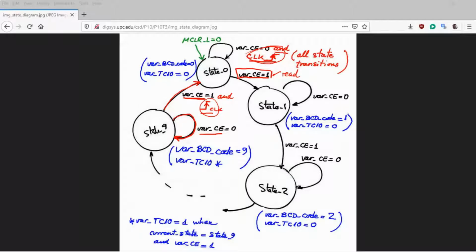So this means that you have to detect that situation as well as you are reading the signal. And to do that detection, you know that you have to go through what is understood as an interrupt to the main program. We will develop that further from now on. But you know, to detect this rising edge of the clock in this circuit, in the end, the bar clock flag has to be set high. That is what has to happen in this kind of circuits, okay? But apart from that, you see that everything is the same.